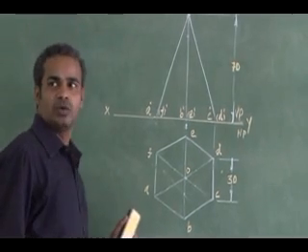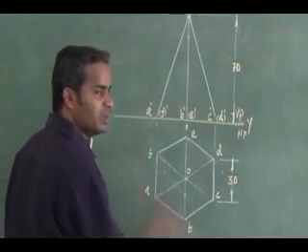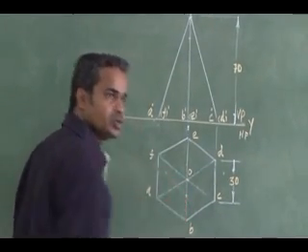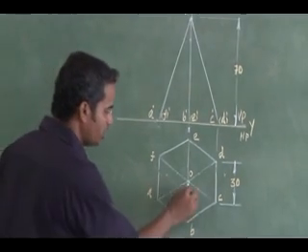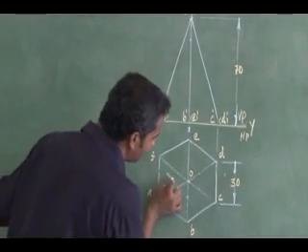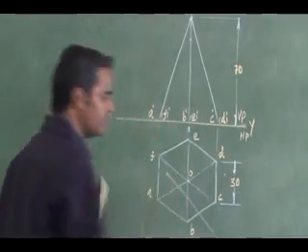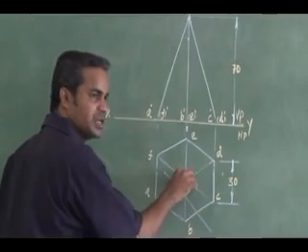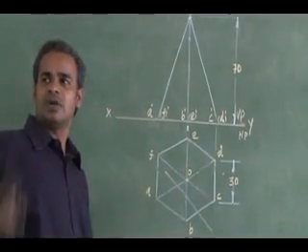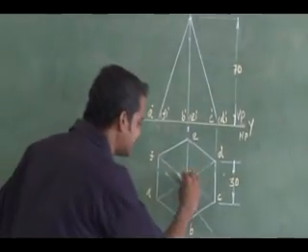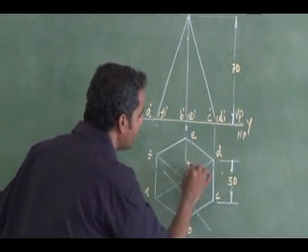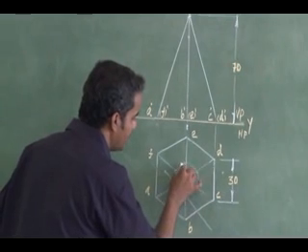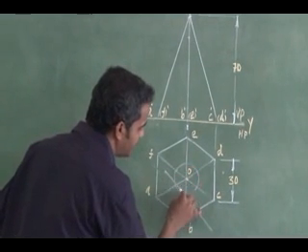All through from the axis, the cutting plane will pass 10 mm away from the axis. So you should not straight away measure 40 degree and mark 10 mm away from the axis and draw it. That is the wrong one. Instead, I can measure 10 mm radius in my compass and draw a construction circle from the axis, that is from the apex here.